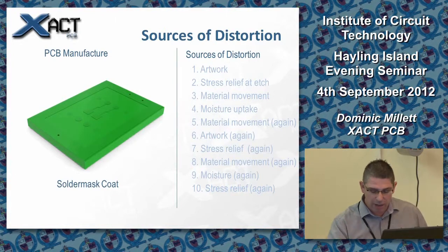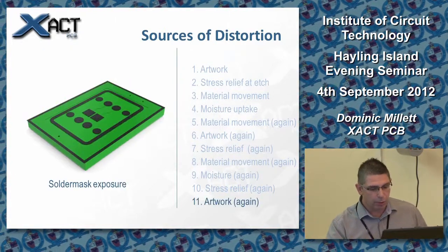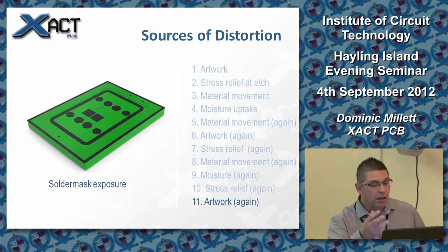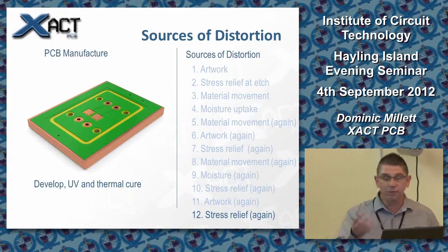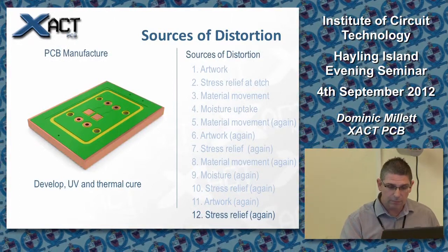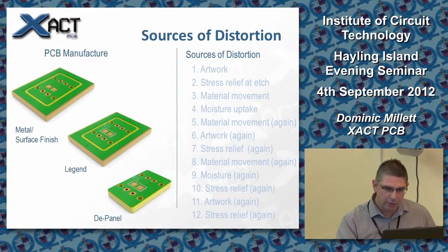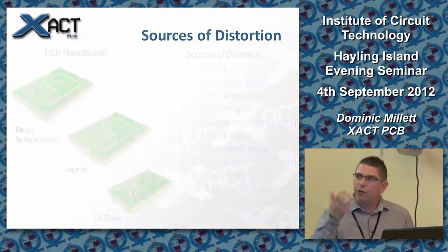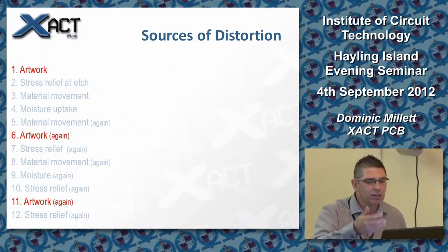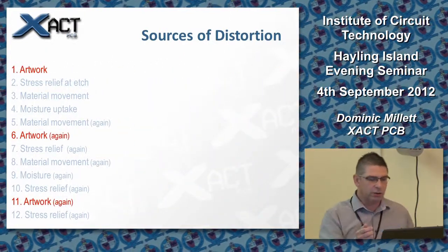Solder mask, exposure, artworks. Thermal effects, now more stress relief on the finished biscuit. And then you have the metal finish, the legend, the depanelization. So all the way through the manufacturing process, there are several sources of distortion, and that includes artworks.